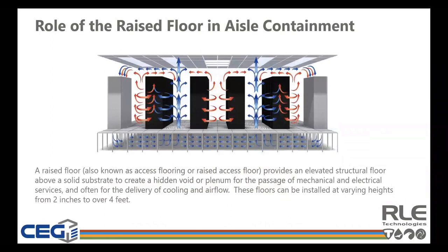The role of the raised floor in the data center is basically to provide a pressurized plenum of cooling air, and through the use of airflow panels, focus that cooling air where it's needed while supporting the weight of the IT cabinets and other equipment. It can also be used as a space for running electrical, communication, and mechanical services. Plenum depth can vary from space to space, but most are between 6 and 48 inches deep.